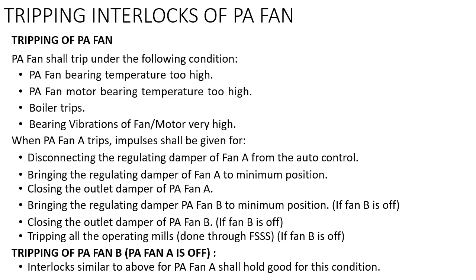Then the tripping of PA fan B if PA fan A is off. The interlocks similar to the above for PA fan A shall hold good for this condition.